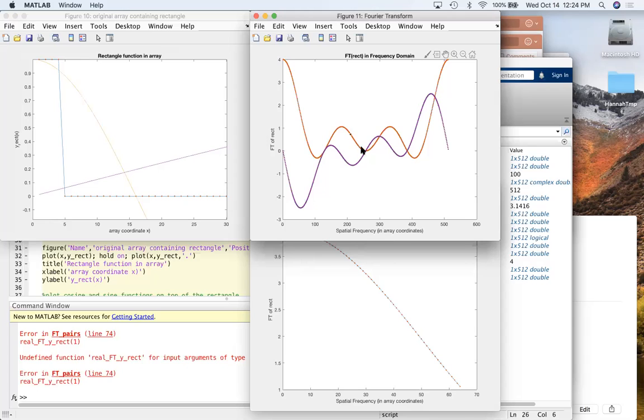And you can see that our values don't get down anywhere close to 0, right? They're overlapping. So this is our first 0, even before our second zero crossing, they're overlapping, right? And so these two replicants are really interfering with each other at this spot.